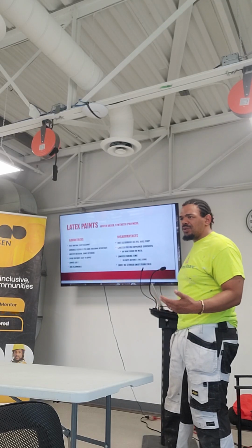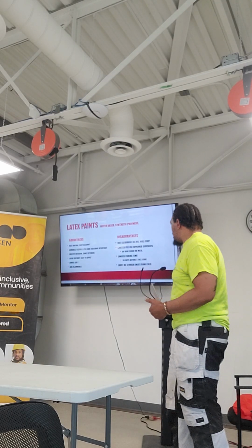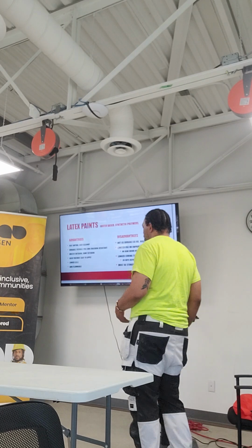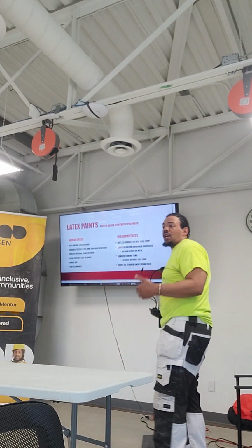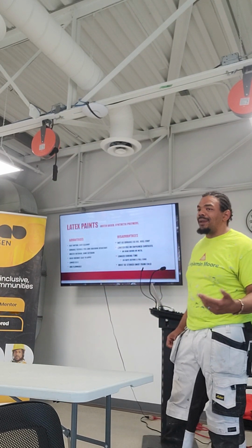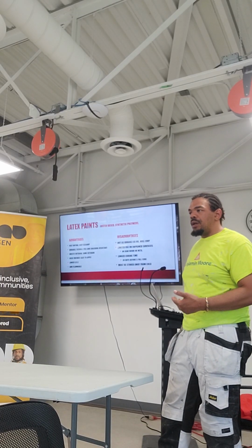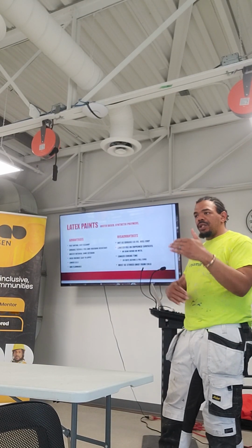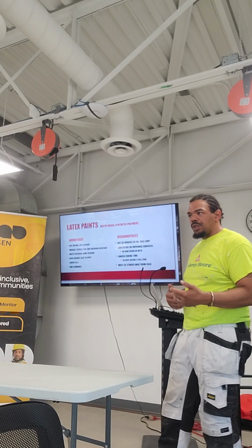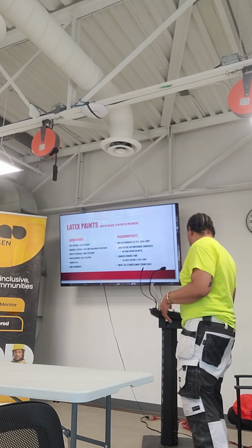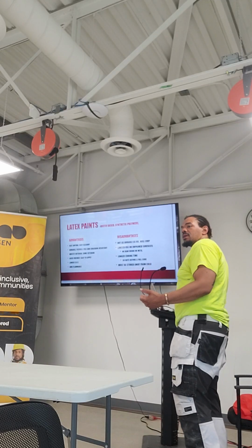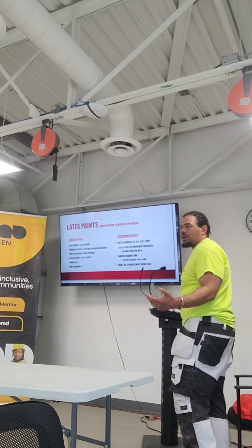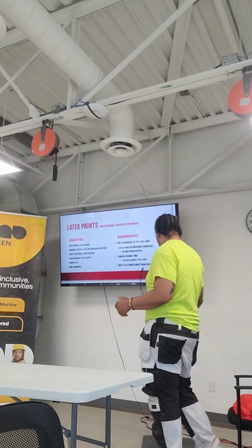It's temperature controlled, it's temperature dependent, the use and the maintenance of it, because you can't use latex paint under a certain degree. You can't use latex paint over a certain degree. There's a window that you have in order to use this material. So it's very temperature dependent. But because it's so user friendly, a lot of people use it in their homes. But for commercial, it's not the best thing to use.